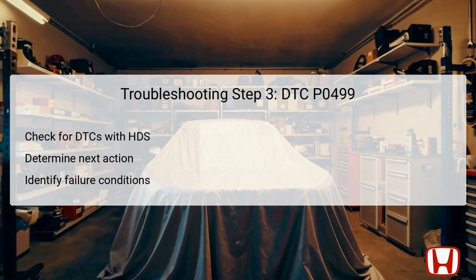This diagnostic step is significant because it allows for immediate verification if the DTC P0499 is still indicated, indicating that the problem persists. If the DTC is confirmed, this directs the technician to the next set of diagnostic procedures specific to addressing P0499. However, if the DTC does not appear, it may point to an intermittent fault, suggesting that the system is operationally okay at that time.